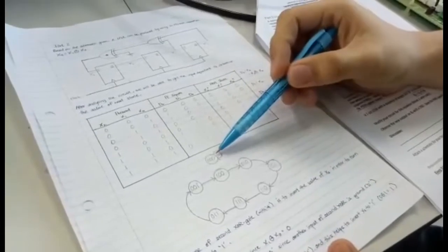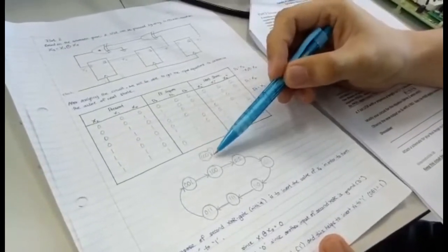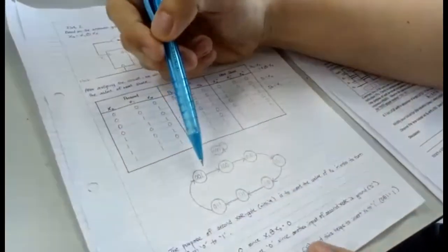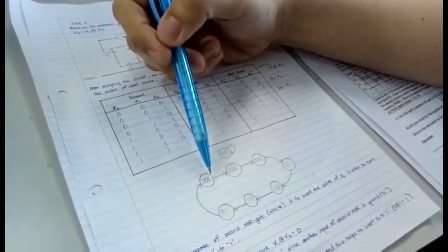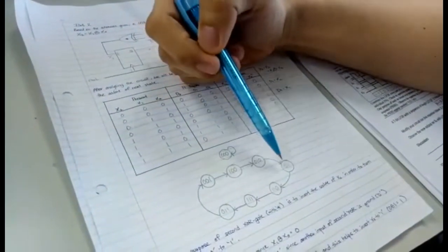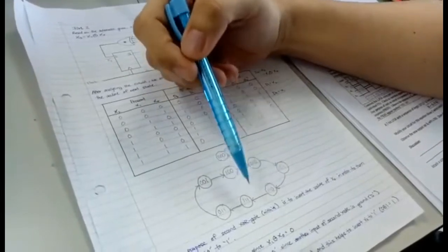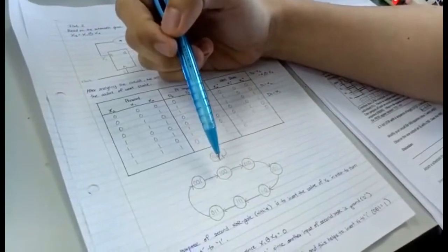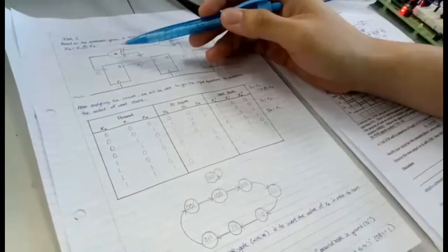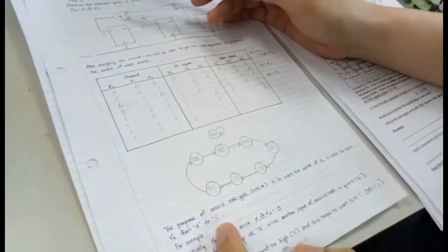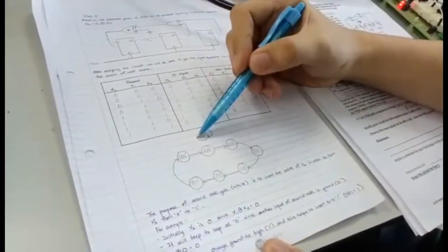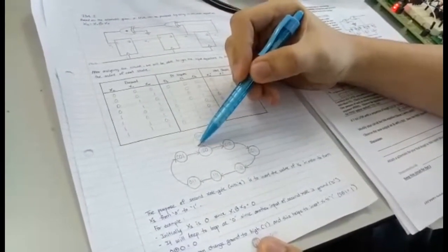The first one is the state staying at 000, and the second sequence goes 001, 100, 010, 101, 110, 111, and 011, and back to 001. The function of the second NOR gate is to help us produce a logic 1 to change from 000 to 100, so that we can verify the result.